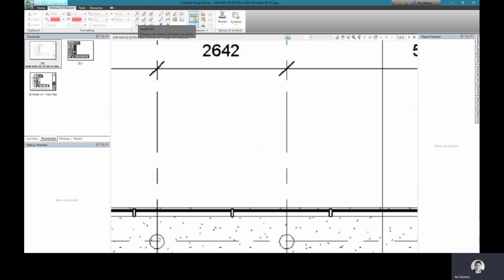On my measure tools, I'm going to click on the length measure. Pick a point on the screen, stretch that across. Now, if I use the Shift control, it will snap to a number of different angles, but it'll snap to a horizontal angle. I'm going to stretch that dimension across, and we'll see that it's 26.3853.